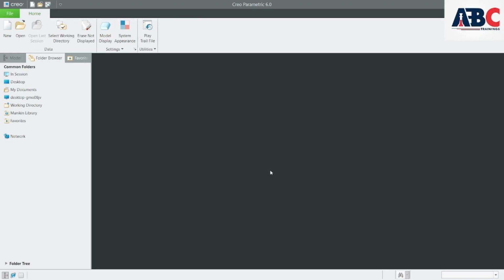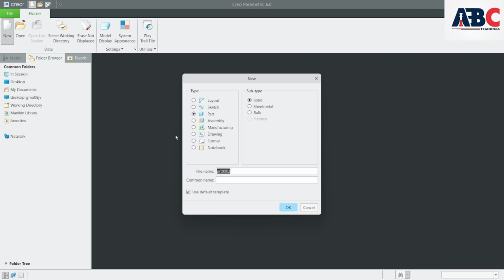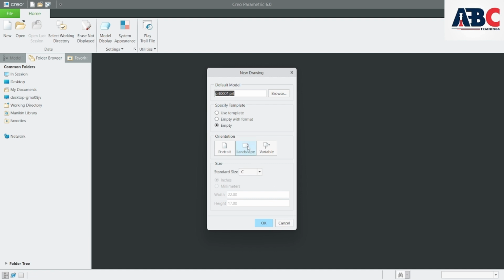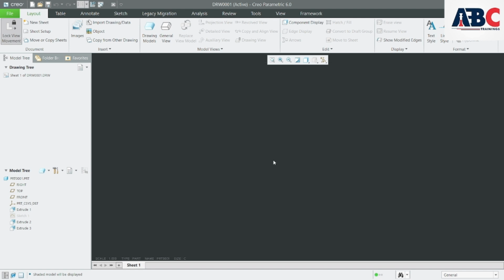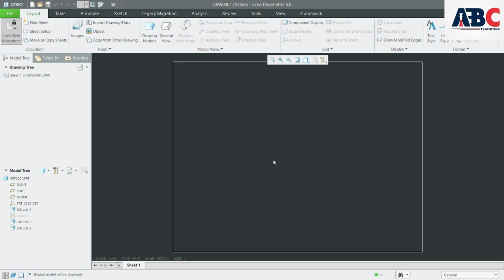Okay guys, now we are in Creo. Let's see how to make projection views and the orthographic views of a drawing. So let's go to New. Here, instead of Part, select Drawing and uncheck Use Default Template. Click on OK. Now see, it's showing us this. Click on OK. Now see, this is the default template, because we haven't designed any kind of template here, like checked by, approved by, who's done the diagram and part, all that.